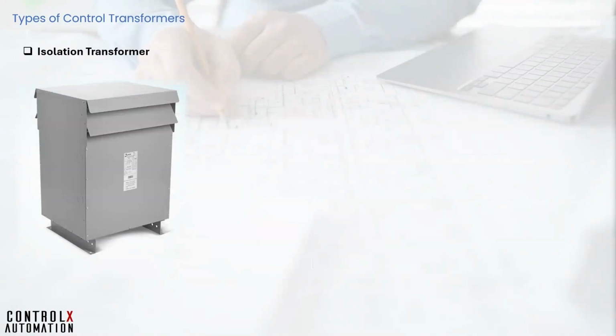Another type of transformer used in industrial applications is the isolation transformer. While not strictly a control transformer, it is still widely used in certain applications where isolation is required from the facility mains power. These are typically three-phase transformers with a 1:1 ratio, which means that the secondary voltage is the same as primary, which is usually the case. However, in certain applications, it could also step down, for example, from 600 volt feed to 480 volt feed. They're usually of higher power rating to supply the machine or process that it is used for.